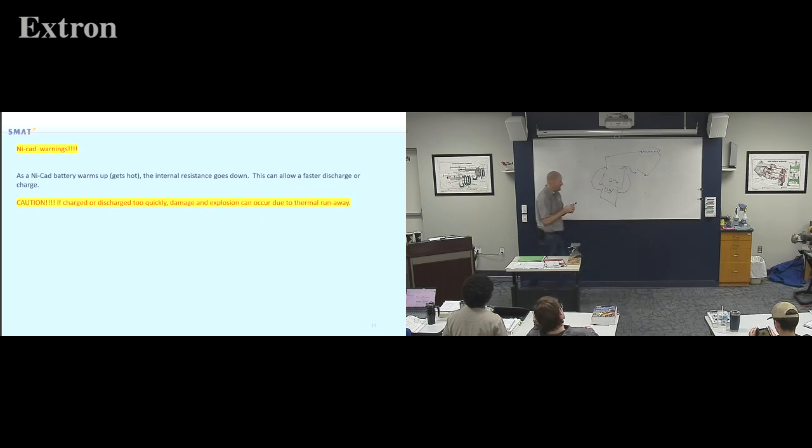All right, so I'm reading 24 volts on my battery. The issue is when I close that switch, my battery voltage is going to drop a little bit. So it's going to change from 24 to something, and it depends on the capacity of our battery and all kinds of fun stuff like that. Let's say it drops to 22 volts. So now I'm running at 22 volts.